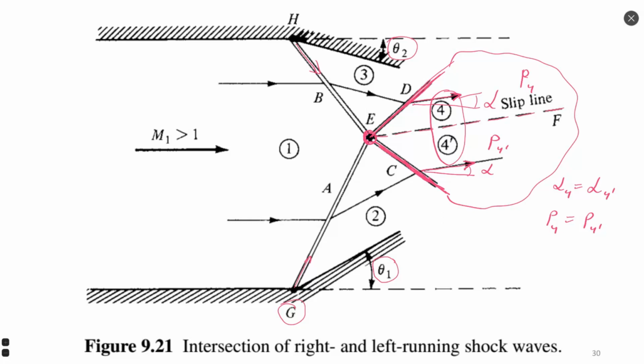Nice question, Luis. Do they also have the same speed? No, these flows do not have the same speed. They have different speed, different Mach number, different velocity. They have different velocity, but since we do not consider shear stress because of the velocity gradient, we do not see mixture between these two flows.